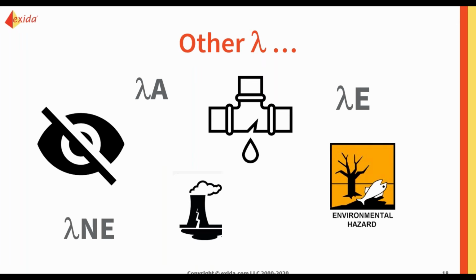What does that mean? This usually just deals with your internal diagnostics. So this failure will still let the safety system work. It will still close that valve if the valve needs to close. It will still detect a failure. However, you might not know if normally detected failures arise. Those detected failures, those DDs, might now become DUs, or those SDs might become SUs, because you don't know about them.